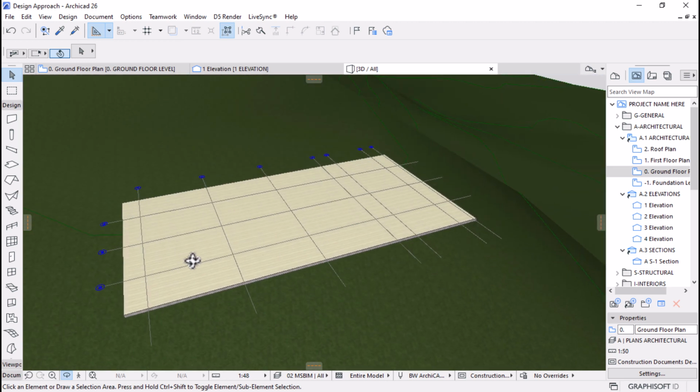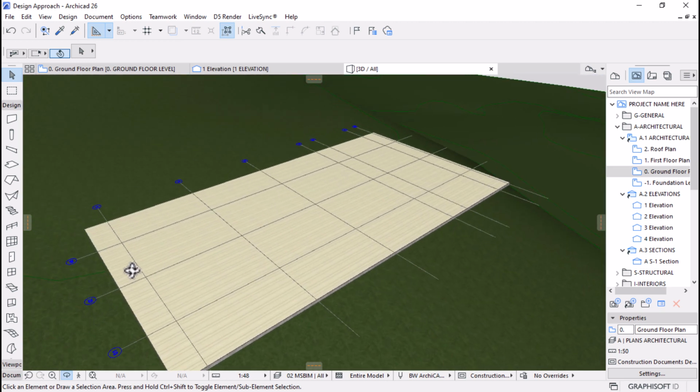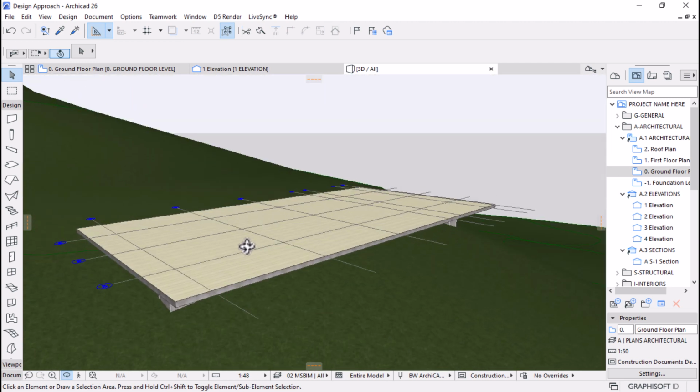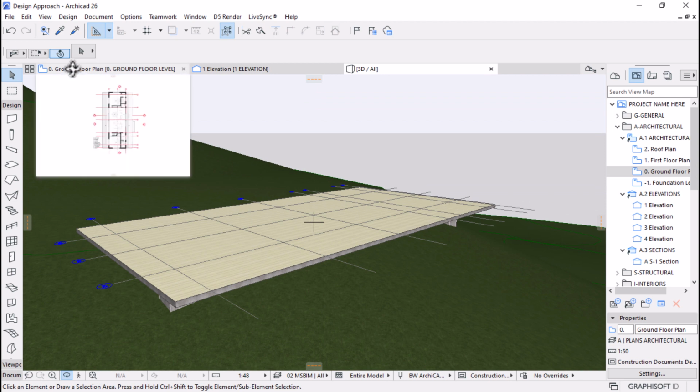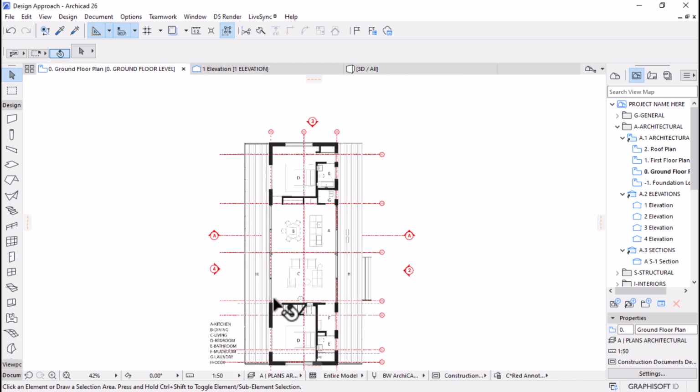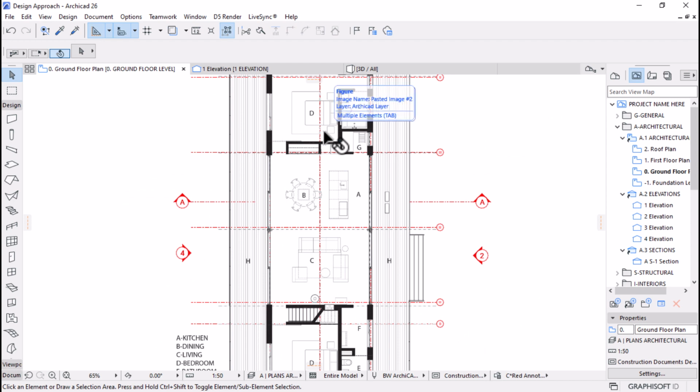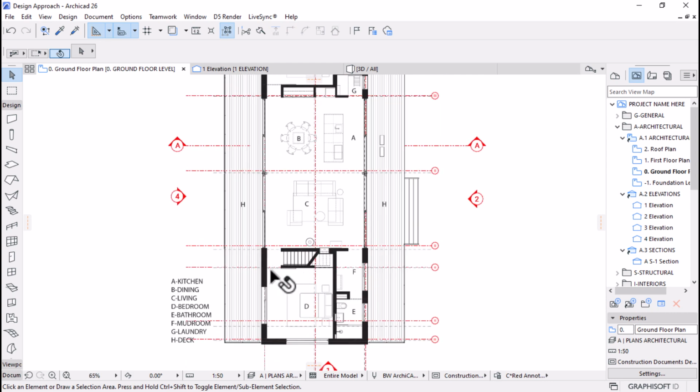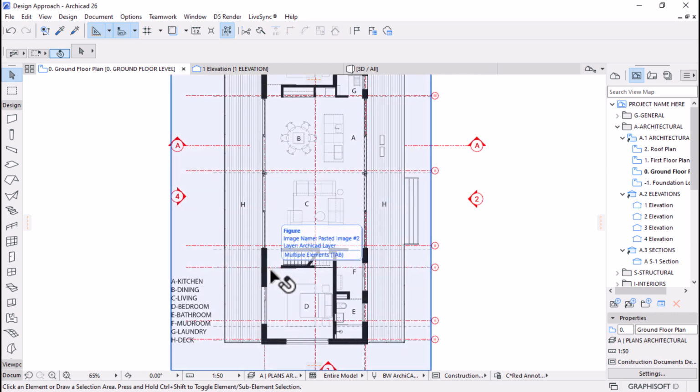All right, so we can now start modeling our superstructure. Let's go back to the floor plan view, and what I want here is to set a composite, because this is more like a timber structure. So let's set a composite for our wall. A composite is a composition or the layering of the skins of our wall.